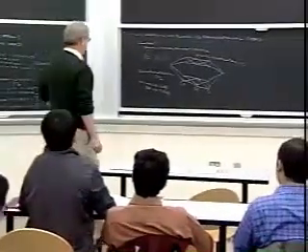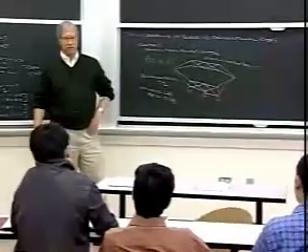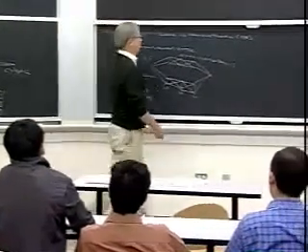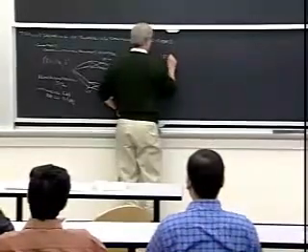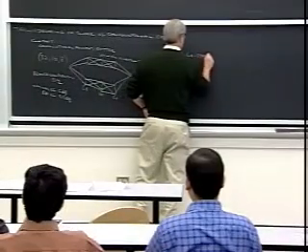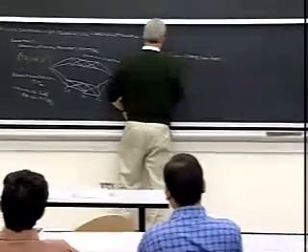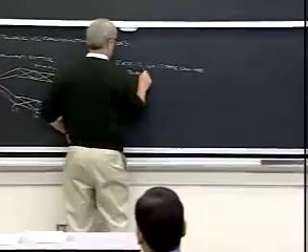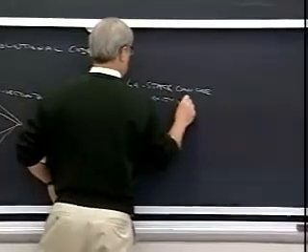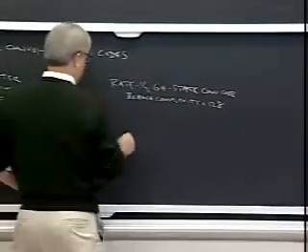And so this was, they call it K equals 7, but in my terms, nu equals 6. A 64-state rate 1/2 convolutional code. So let's take that rate 1/2, 64-state convolutional code, just with the standard trellis. So its branch complexity is 128 at every time, and it has a more regular structure than this guy.